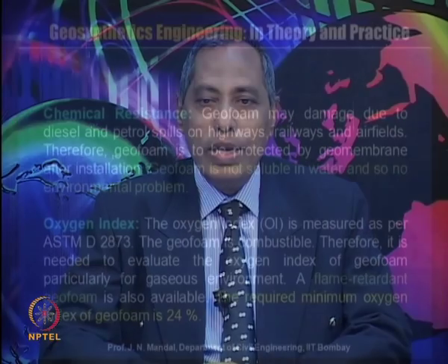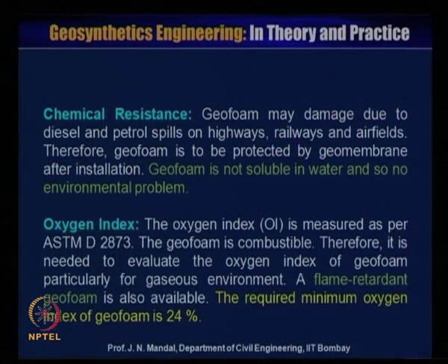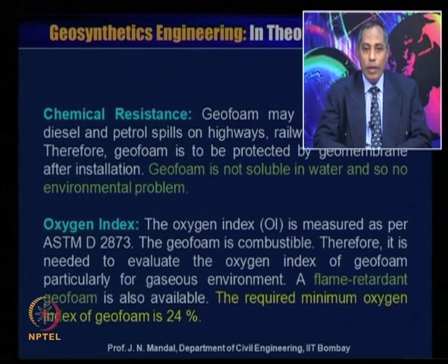Oxygen index. The oxygen index, OI, is measured as per ASTM D2863. The geofoam is combustible, therefore it is needed to evaluate the oxygen index of geofoam, particularly for gaseous environments. A flame retardant geofoam is also available. The required minimum oxygen index of geofoam is 24%.